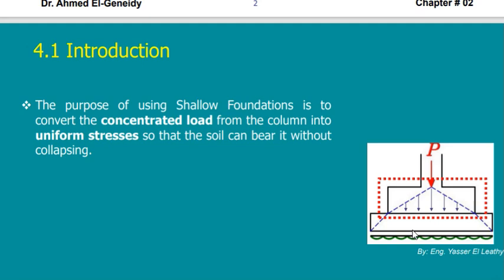So usually we do this. So it is either just 10 centimeters of plain concrete followed by my foundation, or I put, say, 30 centimeters, 40 centimeters of plain concrete, and I consider it part of my foundation to reduce the upper part, which is the reinforced part. This is just a quick introduction.